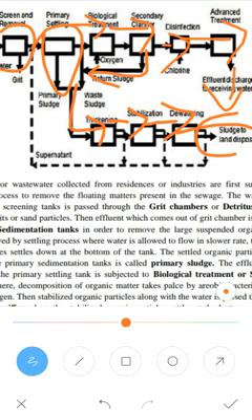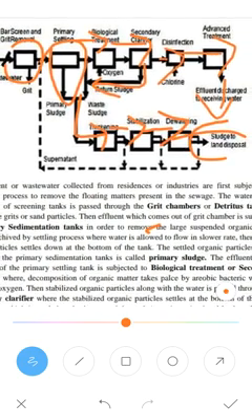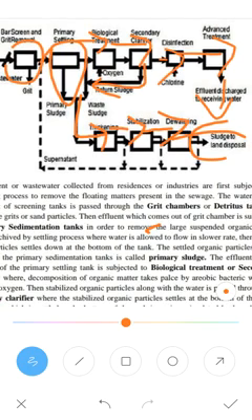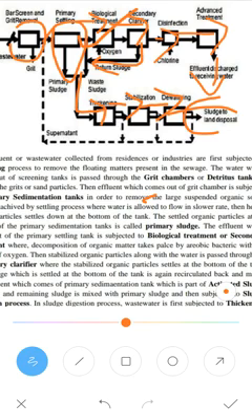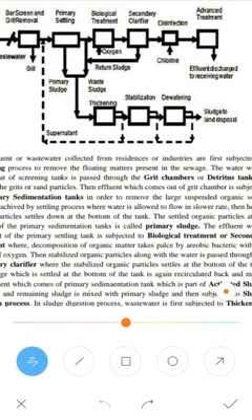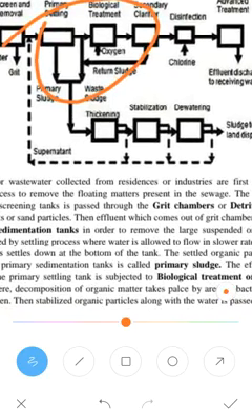That is in order to remove the large suspended organic solids, which is achieved by the settling process, where the wastewater is allowed to flow at a slow rate.